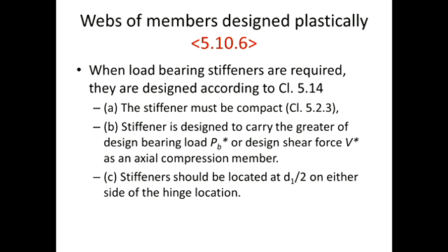If the value of the bearing force and the shear force exceeds 10% of the design capacity of the web, then we also have to make sure that we have stiffeners, and those stiffeners should be able to carry the load which is applied to them, and they have to be at those locations from the plastic hinges.